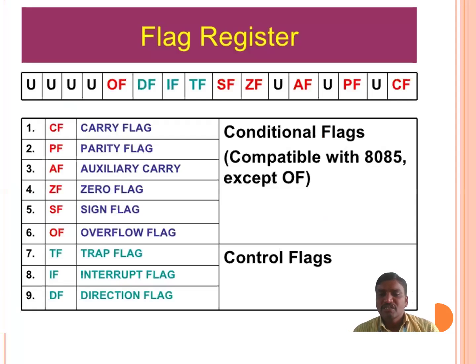How will the processor execute all the 5 lines? Before the execution of each line, the trap flag is set to 1, so then only the current line is executed by the processor. That is the use of the trap flag.